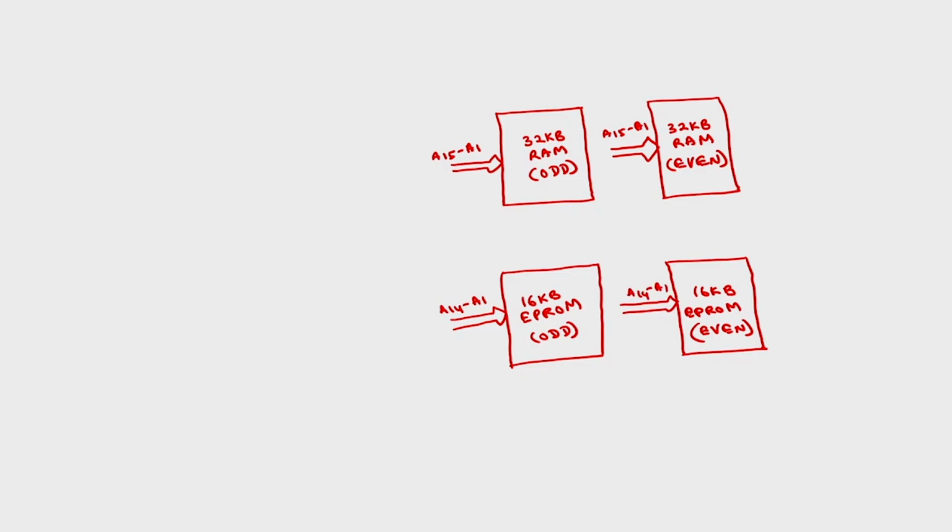So all the 4 buses you are going to connect to the common bus of 8086. Now the question is, how do these 4 devices differ? At any time only one of these memories will be selected, so the data transfer will take place with that particular memory. Even though this common bus of 8086 is connected to all the 4 memories, at any time only one memory is selected, so that the data transfer takes place with the selected memory.